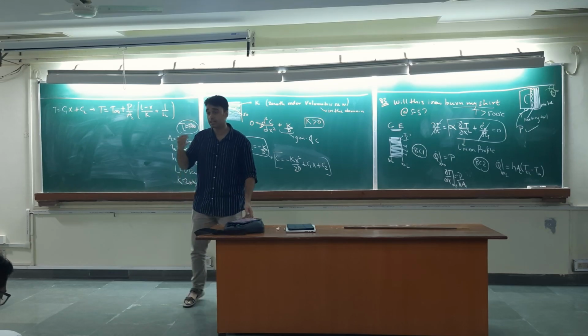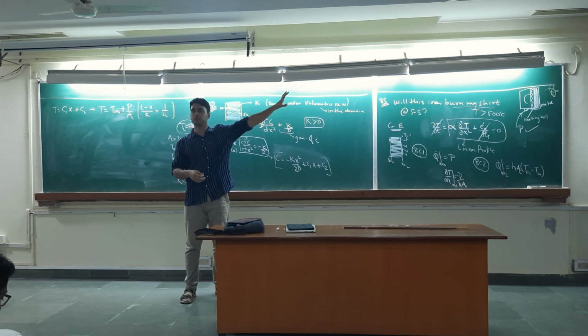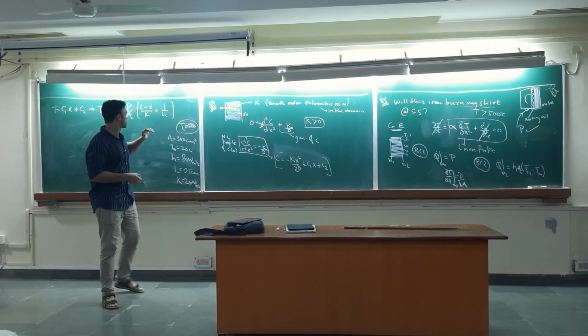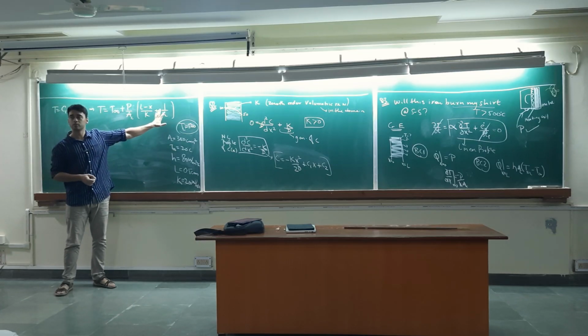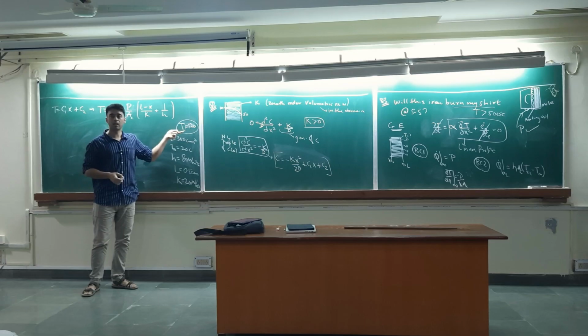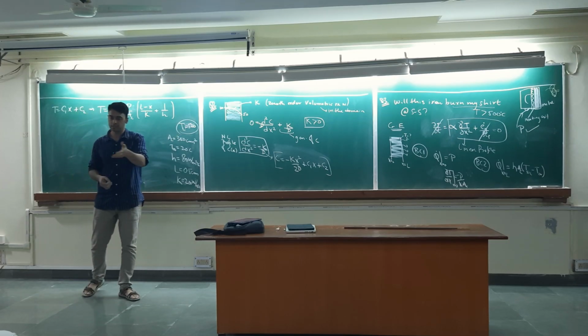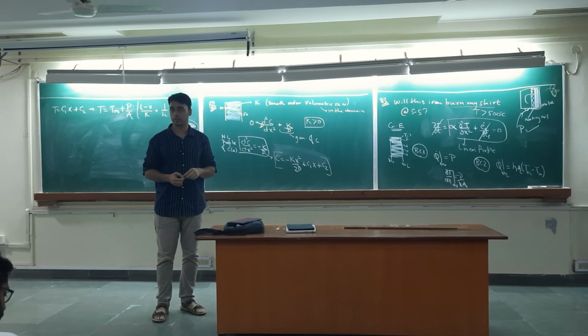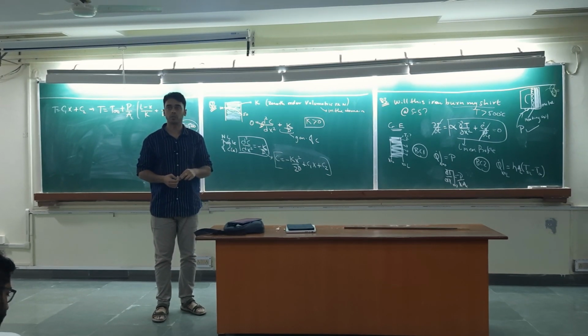Let me tell you what happens if you keep increasing speed like crazy, so that H tends to infinity. Then what will happen to the temperature profile? This term will go to 0. What will happen to TL? Write it down and check: see if TL becomes equal to T infinity, or T ambient, if H is infinity. Just check it.